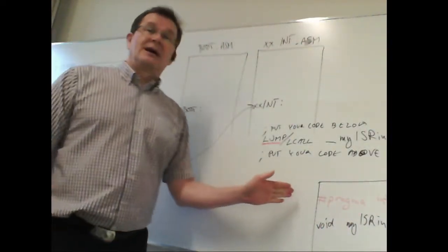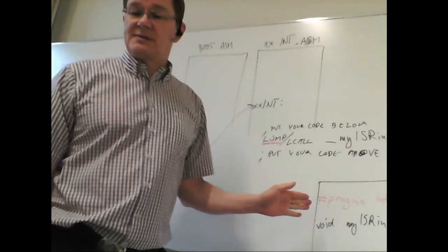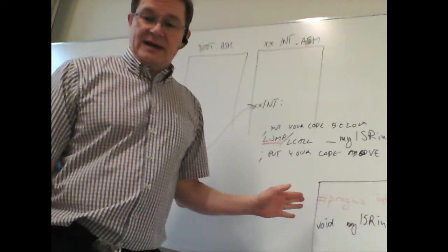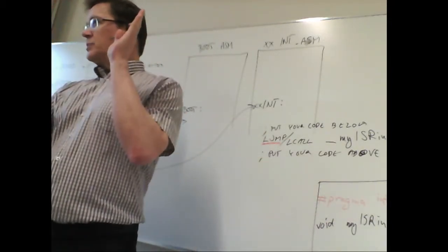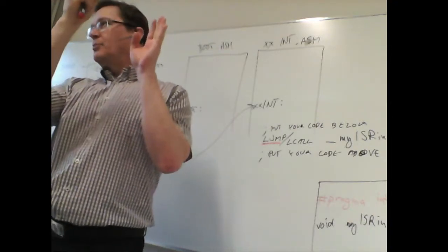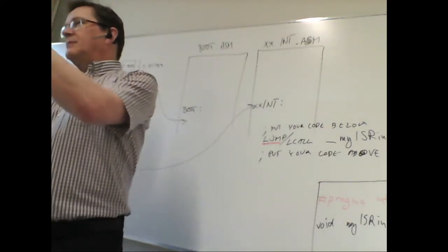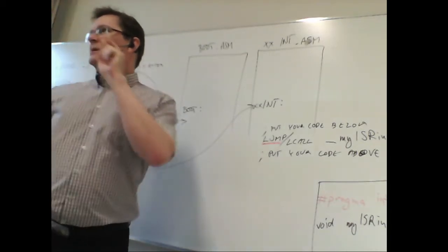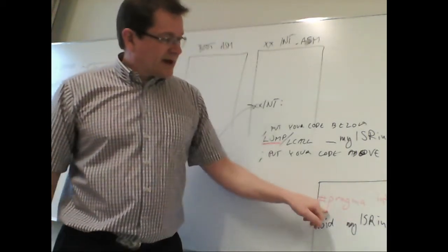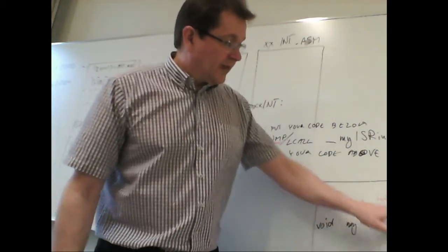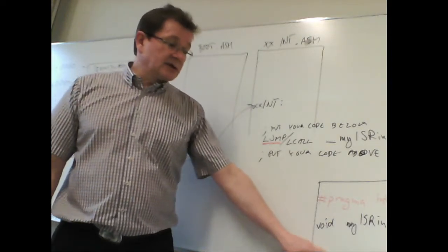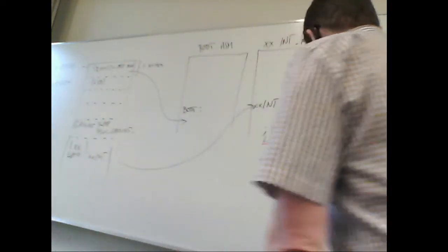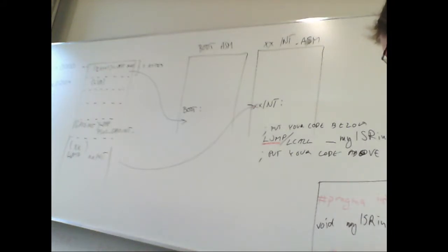It's the same way that in the GPIO int.h file, there's the definition of those IO ports as pragma statements, pragma IO port, that mnemonic, and which address. The same way here we say pragma interrupt handler and the name of that function. Then this actually returns from interrupt, so at the end it uses return from interrupt instead of return.